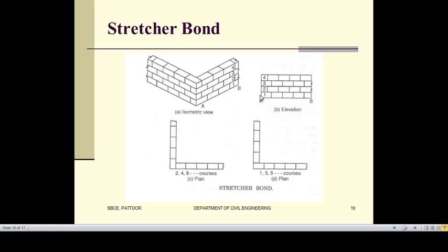And the next layer is the second course. The plan view of the second course is shown in this figure. Alternatively, to stagger the vertical joints, the first one will be a header and the remaining will be stretchers. And looking from this face, all the bricks will be laid as stretchers. So hope you understood. The third course is similar to the first one shown in this plan, and the fourth one is similar to the second one, which is shown in this plan.